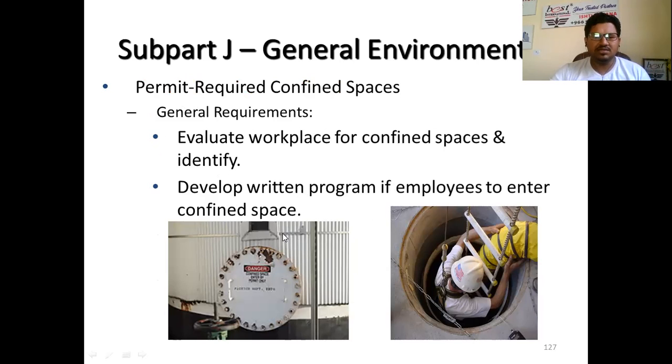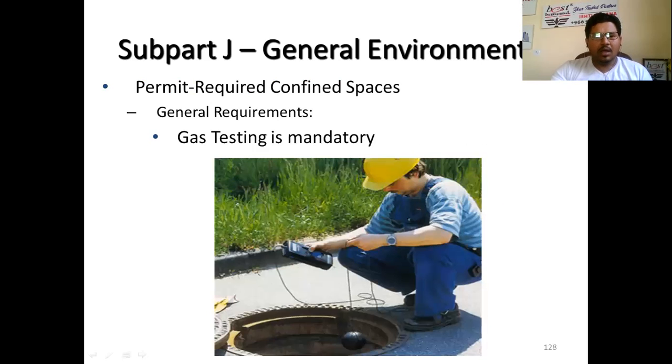Whoever is getting inside must be part of that project, and he must be authorized, and we must make sure he's qualified, certified, well trained, and also signing his CSC log sheet, like what is his name, his ID, why he is going inside, date, time in, time out, and what job he is going to perform exactly. And for confined space, of course, gas testing is mandatory by an authorized gas tester.